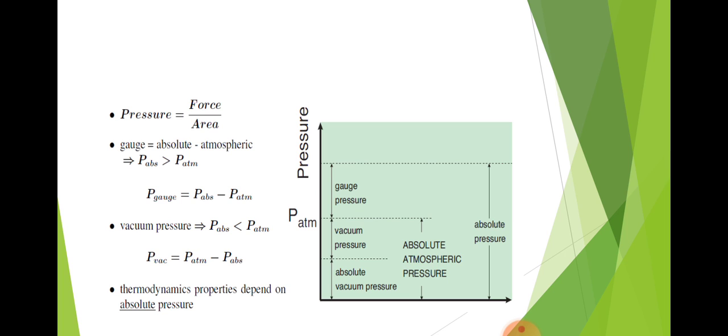Again I said the principle of working of pressure gauges is the same. The pressure in a steam condenser is usually less than atmospheric pressure. A vacuum gauge attached to the condenser measures the difference between the atmospheric pressure and the pressure inside the condenser. This difference is called vacuum and is expressed in millimeters of mercury.